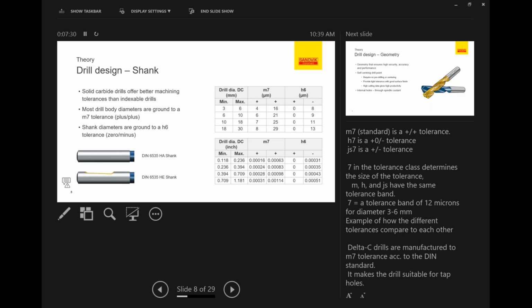So you most likely will be able to hold somewhere around a .251 to .252 hole size, as long as you're running it in a good holder, spindle, fixture, collet, and so on. And then all the shanks are toleranced to a small h6, which accommodates shrink fit or hydraulic holding so that you get proper clamping. So it's important to understand the drill tolerancing.